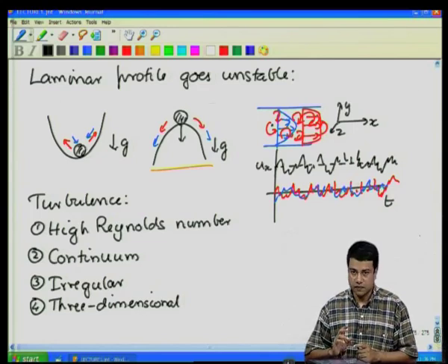That mechanism, I had said, is identically equal to 0 in two dimensions, because I have a two dimensional velocity profile with two components u x and u y varying in the x and y directions. The vorticity vector is perpendicular to both of these, so it is in the z direction, and because of that, that mechanism is absent in 2 dimensions, because I have omega z and the strain rate is in the x and y plane. So, in that particular case it is equal to 0.